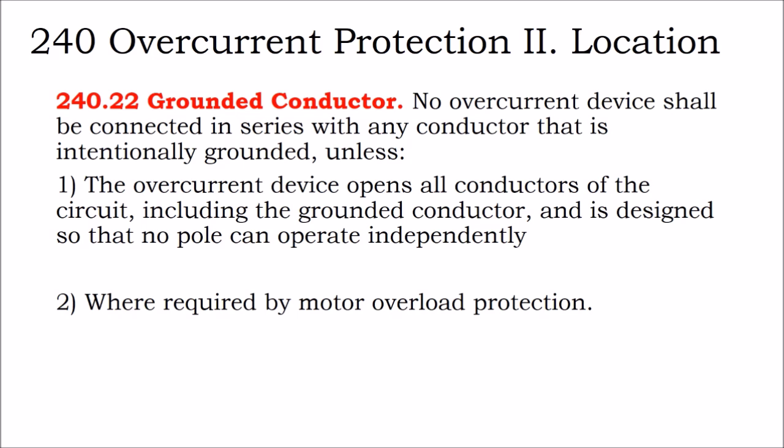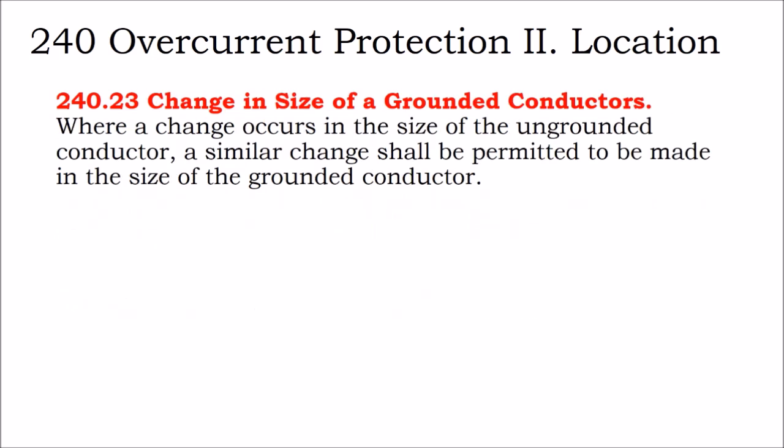A similar thing can happen with your main service panel and your main breaker. The only exception would be on a motor circuit. You may put an overcurrent protection device into that grounded neutral, or you might have a grounded negative to provide some additional protection of your motor.